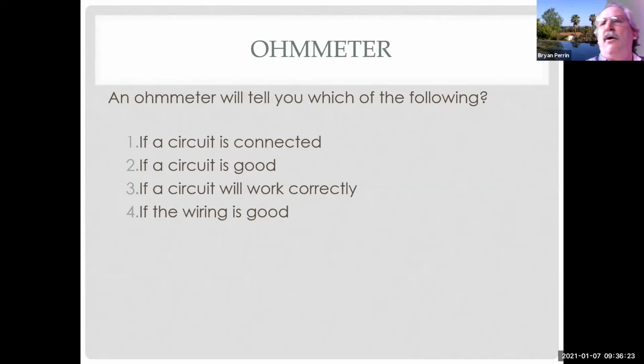Going back to the flow charts, a lot of flow charts use an ohm meter, and they have you check resistance and things and then assume it's good because it's written by an engineer. And in the field, we find that that's not the case. So what we want to do is actually test things dynamically, test things when everything's connected. And that's really how we find the problems.